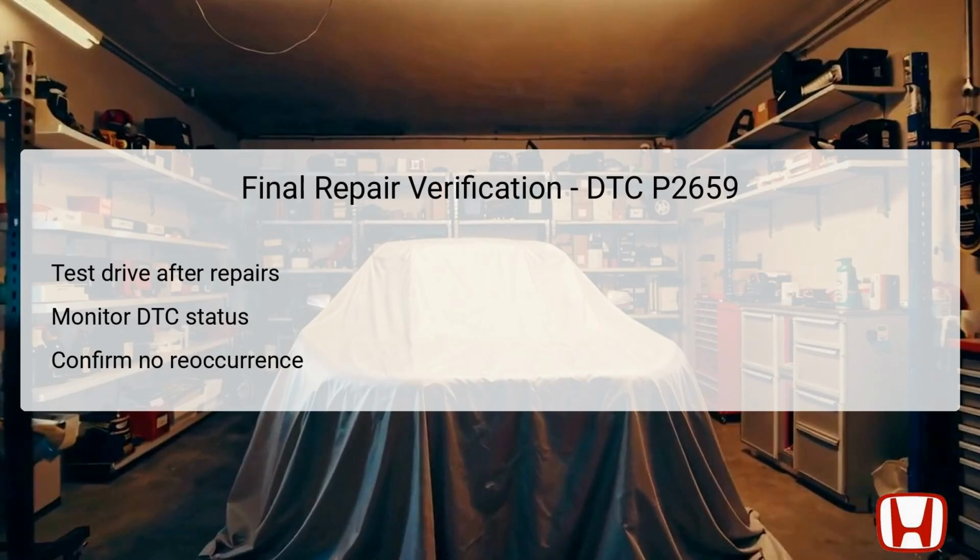Once repairs and any replacements have been made, it's imperative to verify that the issues associated with DTC P2659 have been effectively resolved. This involves conducting a test drive of the vehicle under normal operating conditions to assess performance. During this drive, it is necessary to monitor the vehicle's computer for any indication that the DTC reappears or if other issues arise. Following the drive, the technician should use the Honda diagnostic system to scan for DTCs again. The absence of any DTCs post-repair suggests that the issue has been successfully rectified.